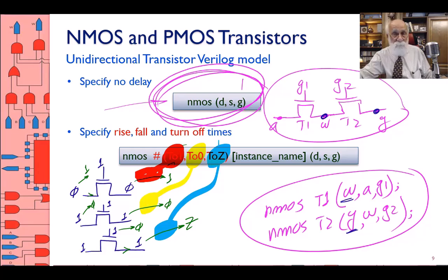How about X? What happens if I have 2 transistors, one driving 1, one driving 0, and at one point the output becomes X? What's the X delay? It's the larger of the 3. What if I drop one of these? The one that is dropped is the larger of the 3. What if I only put 1 in there?